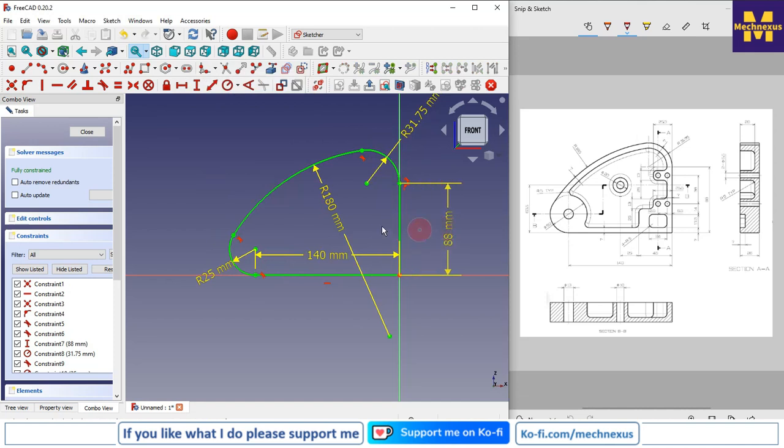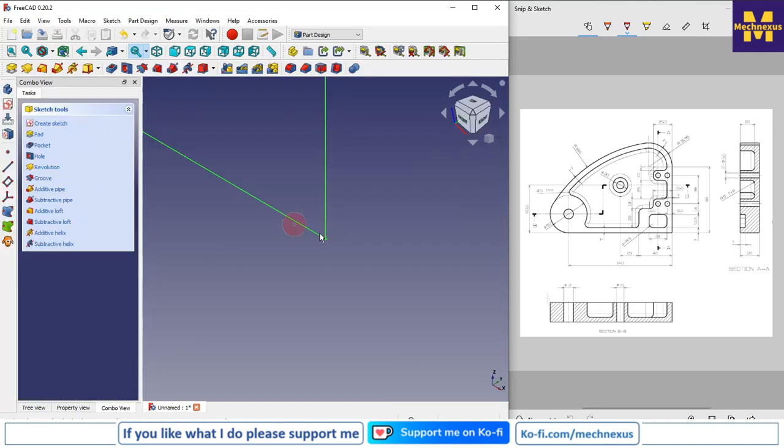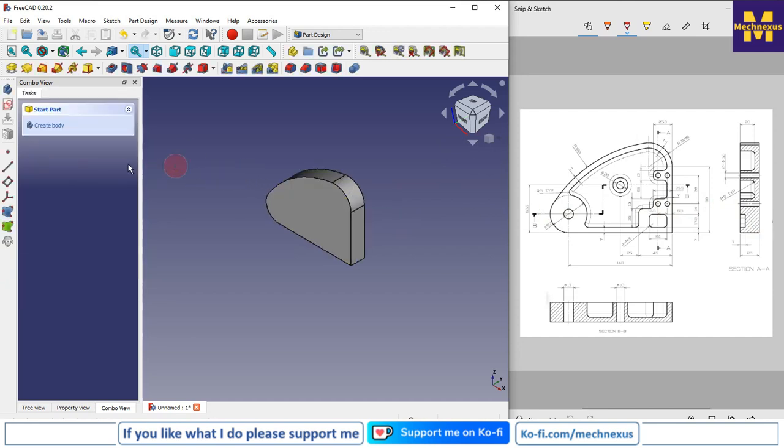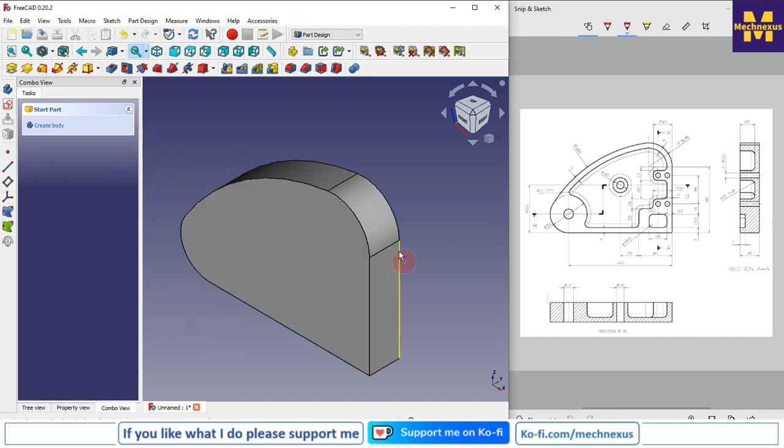So this is our base profile, and I will come out of the sketch, and I will go with a pad, and I will pad it in one direction with a thickness of 26. Okay, so this is our base feature.